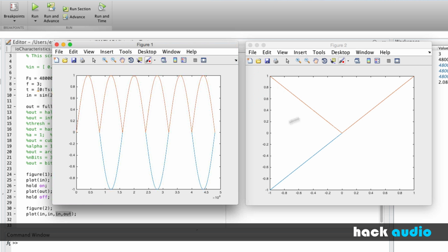We have these lines instead of looking at the waveform. So our blue line is our input signal without any processing, goes from -1 up to 1. We can see the distortion that occurs when we have any negative amplitude down here gets reflected up to be positive amplitude. So if we had an input amplitude of -0.5, our output amplitude is going to be positive 0.5.